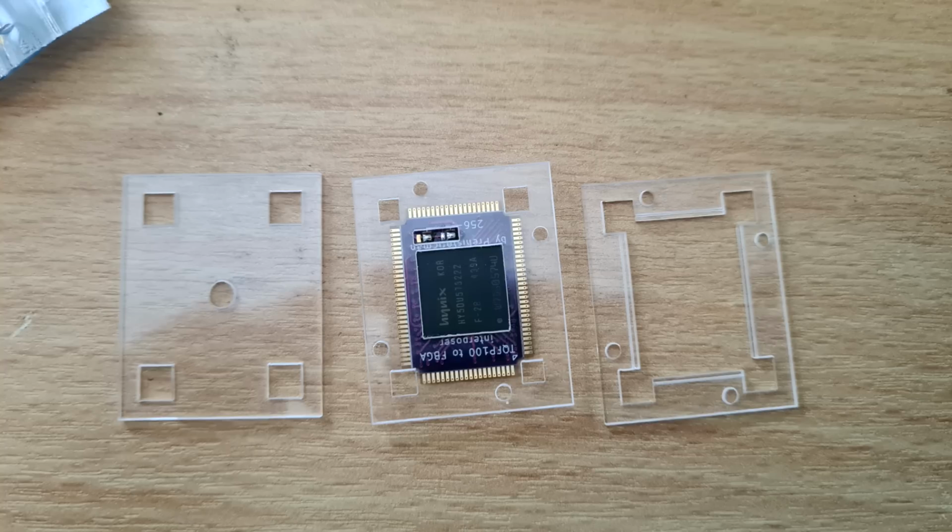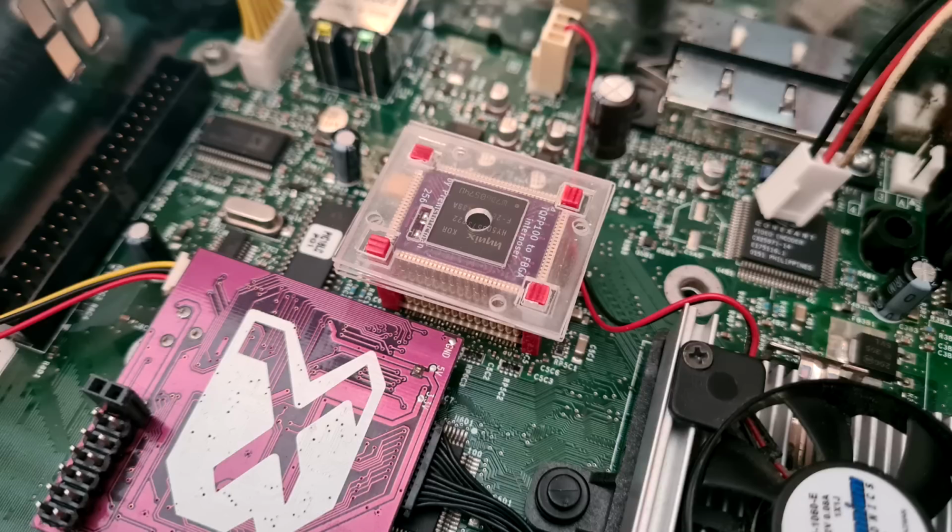Firstly, the alignment of the BGA to the pins on the interposer is not precise. They are on different layers. So the BGA is positioned on the top layer of the PCB, and those pins are on the middle 2 layers. And these can have some mismatch.